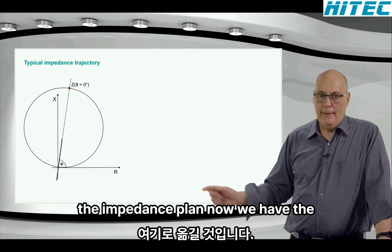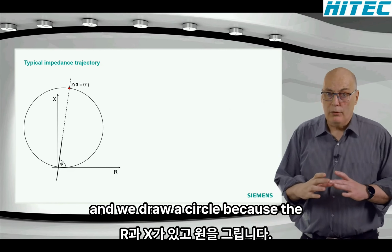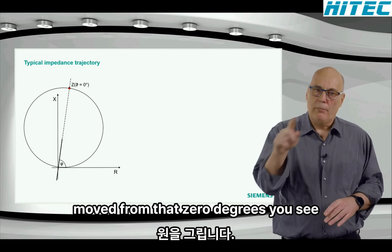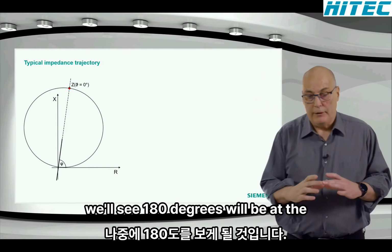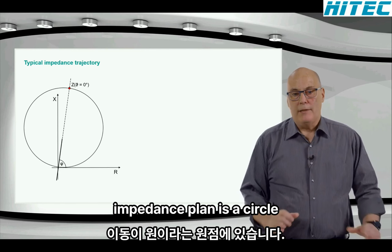the impedance plane. Now we have the impedance plane R and X, and we draw a circle, because the trajectory of the power swing as we move from that 0 degrees, you see right at the top 0 degrees, to later on we'll see the 180 degrees will be at the origin. That trajectory you move on in the impedance plane is a circle.